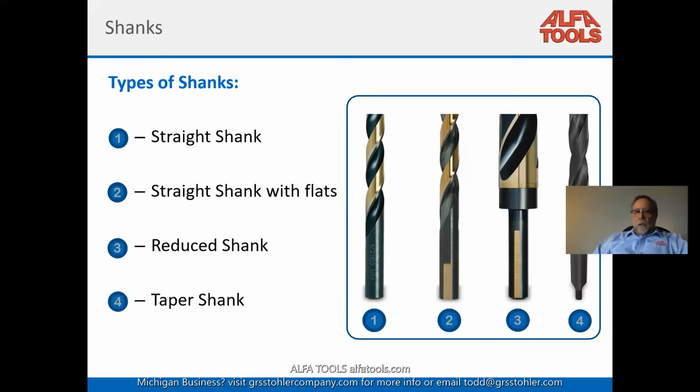You use number 3, a reduced shank drill. Those drills are available up to 1.5 inches with a 1/2 inch shank. And with a 3/4 beefier shank, they're available up to 2 inch. So with this kind of tool, your portable tool, you can go from extremely tiny up to actually 2 inch off a 1/2 inch shank.